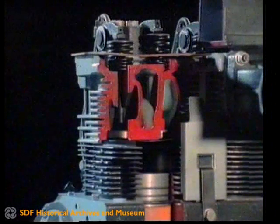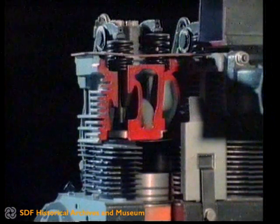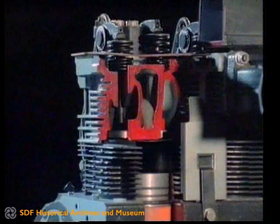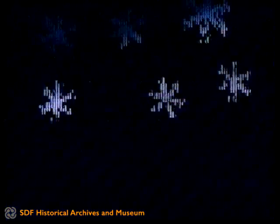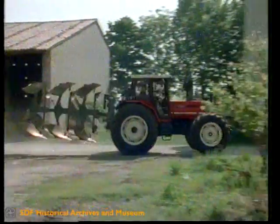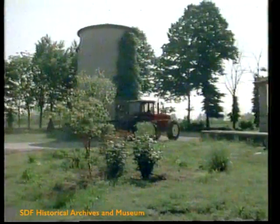The cylinder finning acts as a thermostat. In fact, it naturally regulates the heat exchange unit with the air, according to the external temperature, so as to maintain the service temperature at a constant level independently of the climatic conditions. Adaptable to every climate. Absence of any kind of mechanical thermostat, and so as to reach the working temperature in a short time. Rapid power availability.